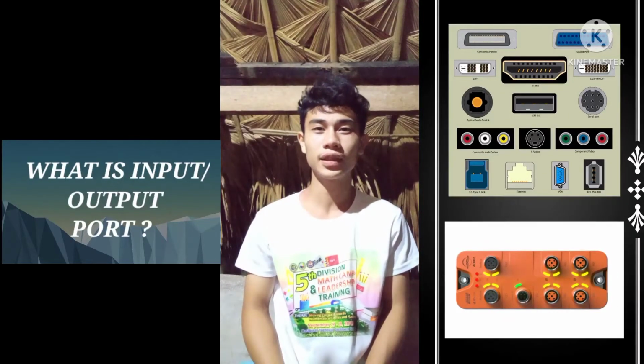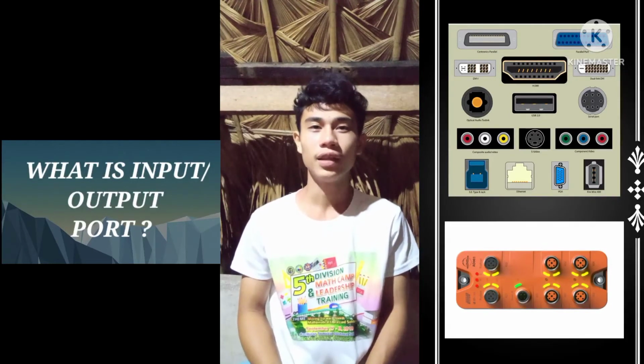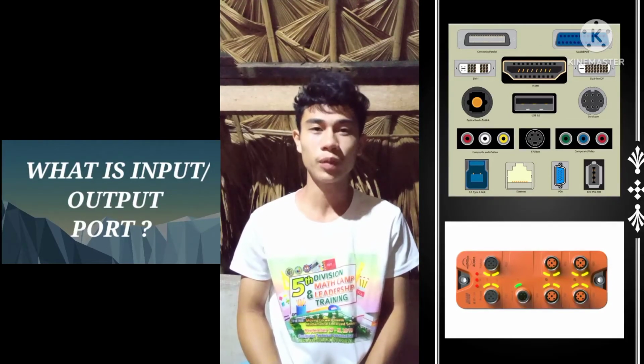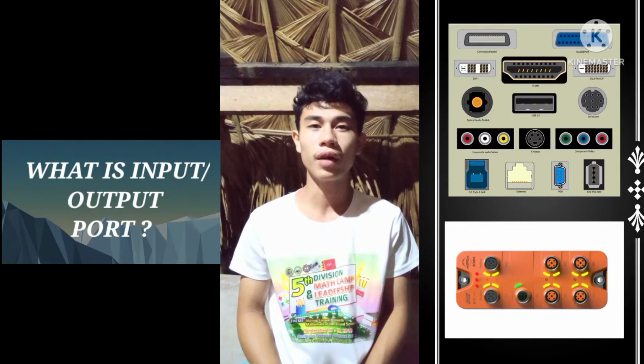Input or output ports are the connection between the CPU and the peripheral device on a motherboard. There are two complementary methods to perform input and output processes: memory-mapped input or output, MMIO, and port-mapped input or output, PMIO. Alternatively, you can use dedicated input and output processors called channels on mainframe computers, which execute their own instructions.